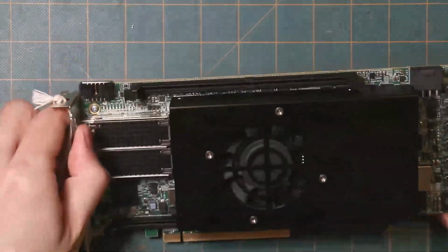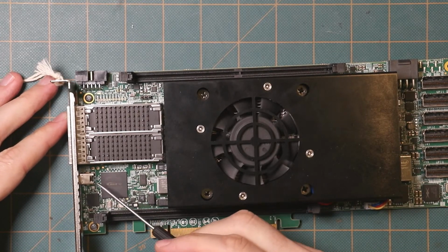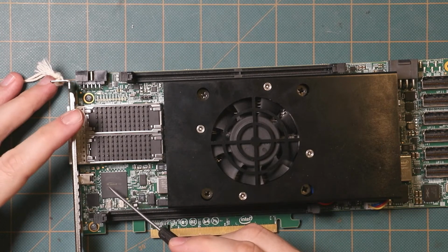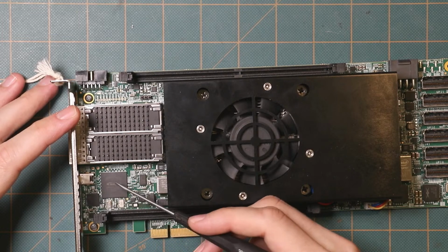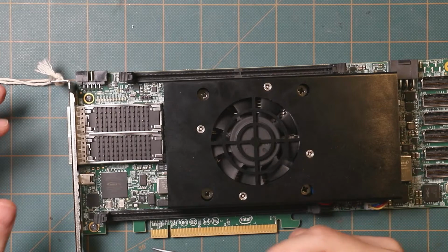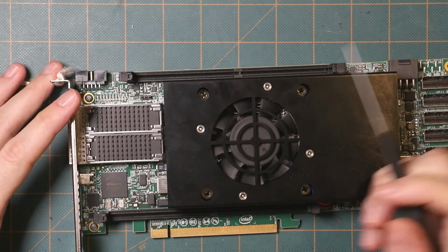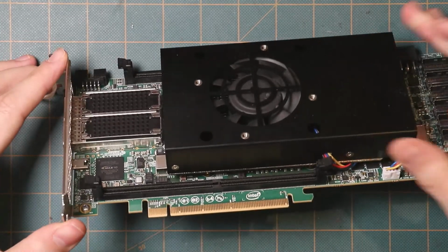So the other thing that these boards have on there is there's a Max 10 board management FPGA. So this provides both the USB JTAG. Well, actually, there's a Max 10 FPGA, there's a Cypress chip here, and then a USB port. So the combination of those gives you the USB JTAG, and then I think this also has a component for loading the bit file, or the Intel equivalent of a bit file, onto the FPGA. And then there's a JTAG connector over here. And yeah, that's about it.